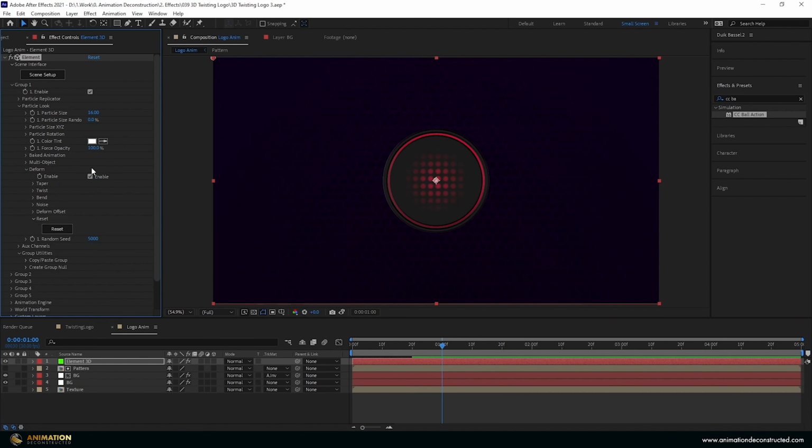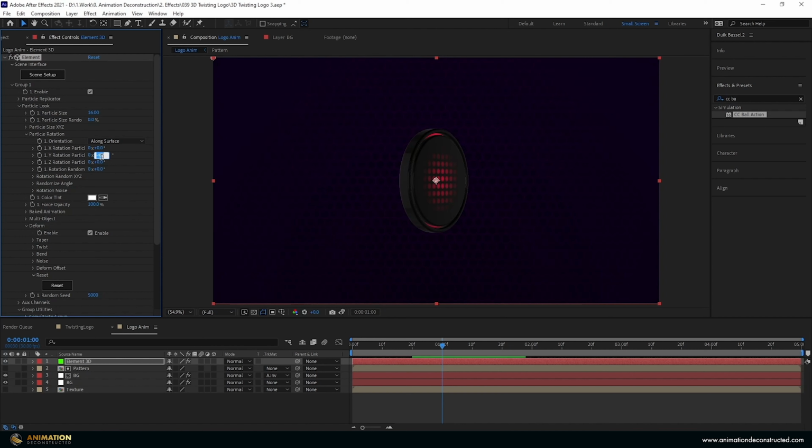So we drop down the deform and we also drop down the rotation. We'll get all our options that we need. And we're going to rotate this on the Y. Let's say about -80, and then come down to the deform, and I want to use twist in this, and we're going to enable twist. And just note that every time you enable something, it's going to take more RAM to use. I'm going to twist this on the X, so let's just drag forward, say about 36.